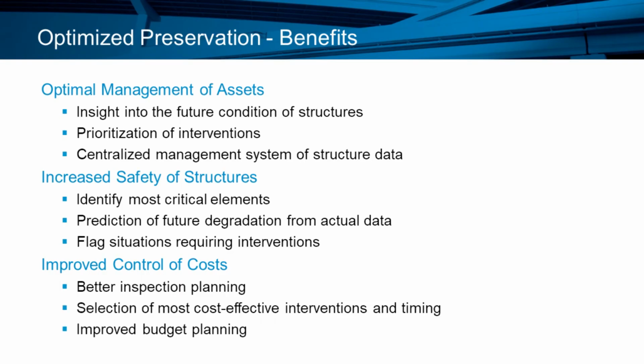For example, as in the last presentation, when we were talking about washing bridge decks, one thing that can be done is to take chloride samples at different intervals, and then you can compare the effect of washing a bridge deck over a given period of time. So in that case, this can be directly related to service life by means of modeling. So it's integrating all aspects of bridge preservation strategies.